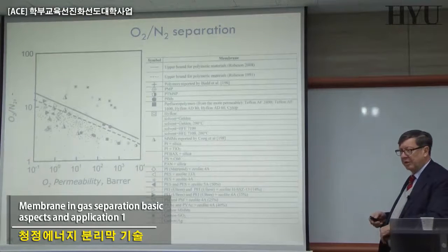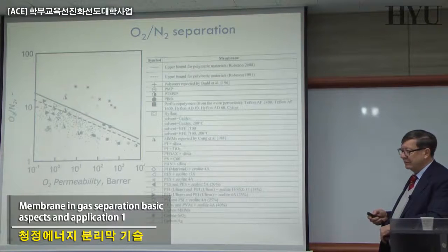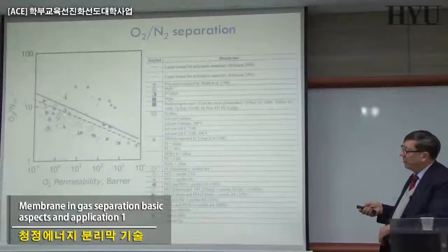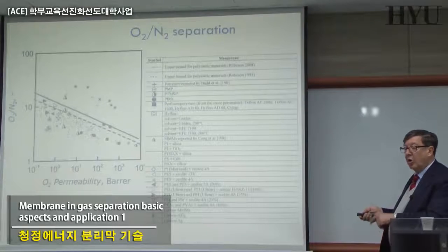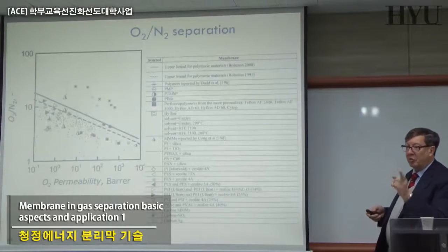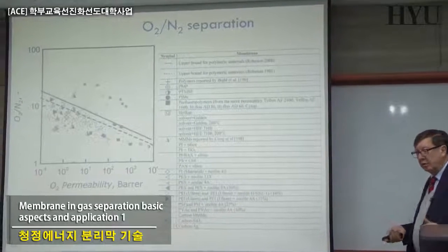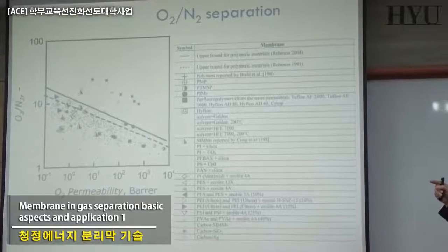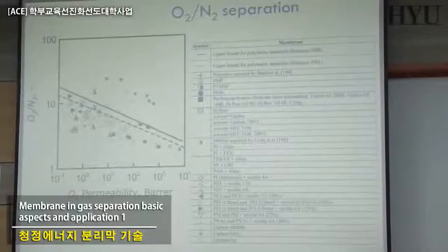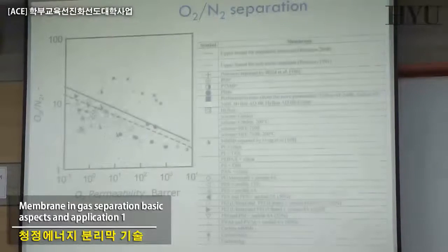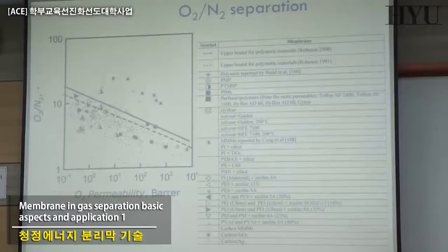You probably heard something already in the previous lectures, but some areas are already well established. For example, when you want to separate oxygen from nitrogen, or better, nitrogen from oxygen, this is a dominant technology today. That means that for non-cryogenic nitrogen production, the competition with the cryogenic is only related to the size of the plant.